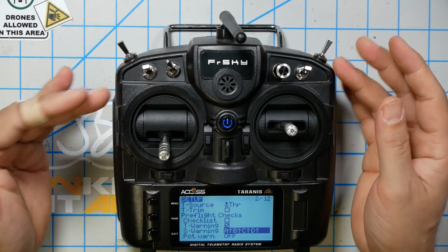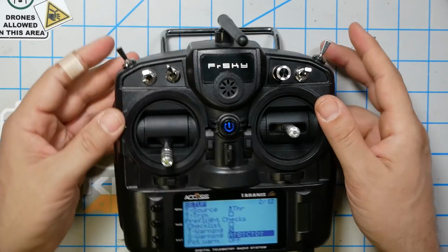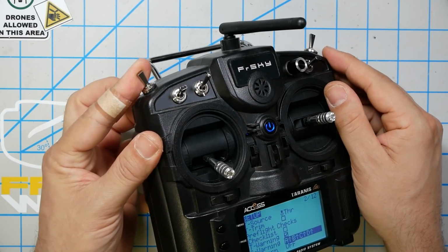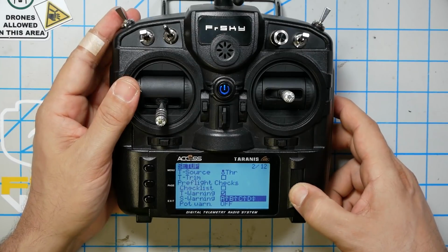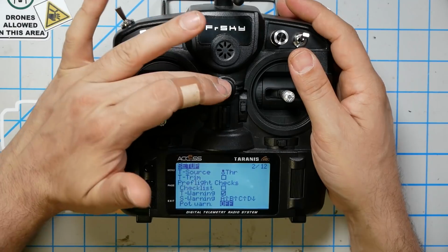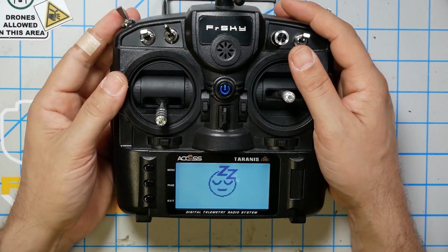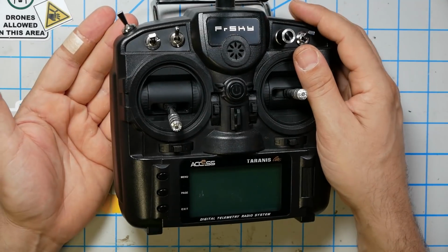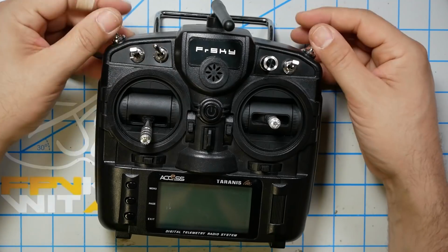I'm going to put all my switches in their default position. So all the switches are going to be pushed away from me, except for the arm switch, which is pulled towards me into the disarm position. And then I'm going to long press the jog wheel, and it will update the default switch positions to match my current setup. And now I will not get that switch warning when I turn the radio on again, unless the switch is in the wrong position, in which case I need to put it in the right position.